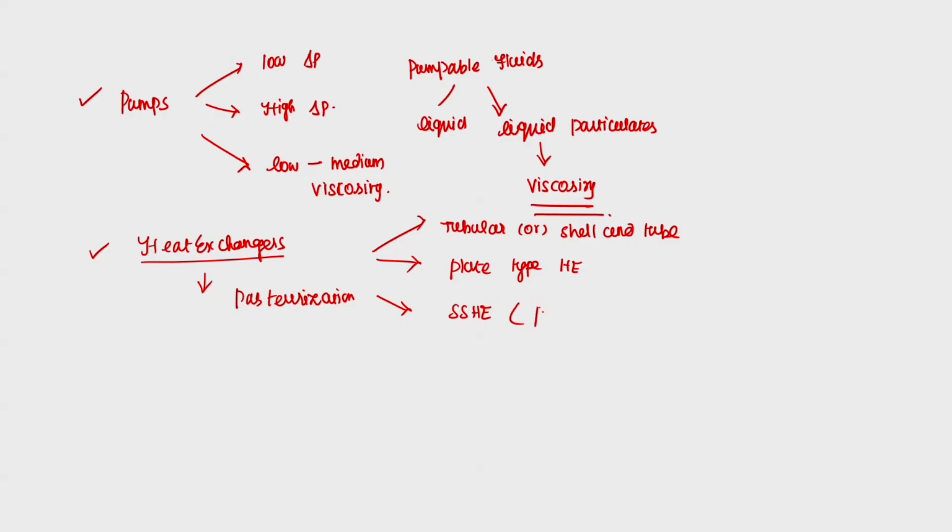This is used for particulate solids, because it has the rotor tube, and in this the blades are attached. These blades rotate, and it also takes care of good mixing on the product side, right. When liquids contain particulate solids, this is the most wanted one.